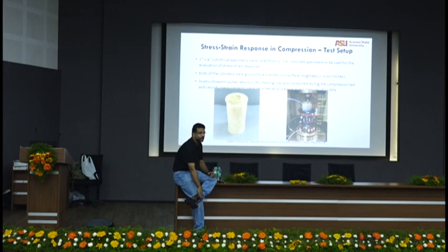Structural properties are very important, right? So you need to examine what the structural properties are, what the constitutive relationships are, so that we can turn the material properties into design data, design tables. Finally, when you do a structural design, you want to know the elastic modulus, the Poisson's ratio, the flexural strength, the stiffness, right? You want all those parameters.